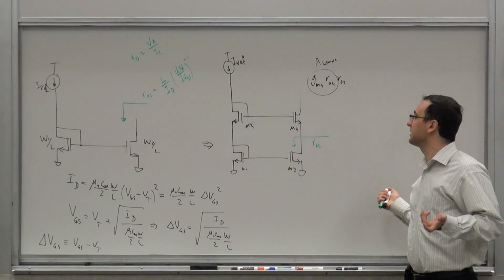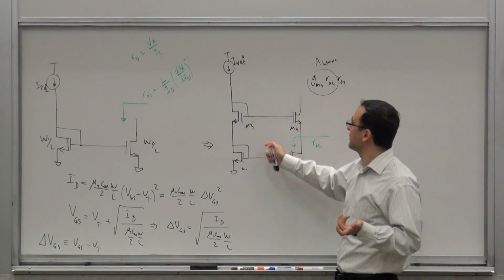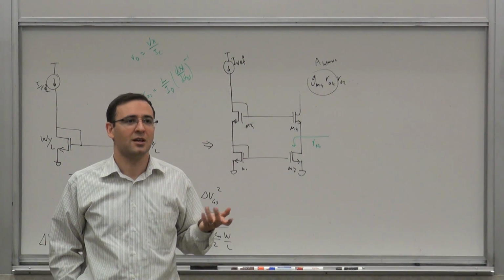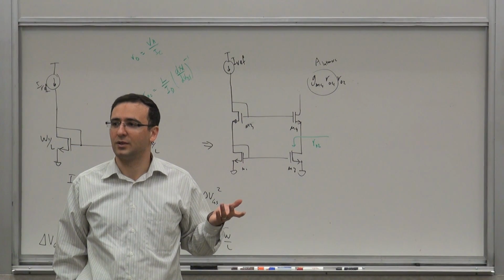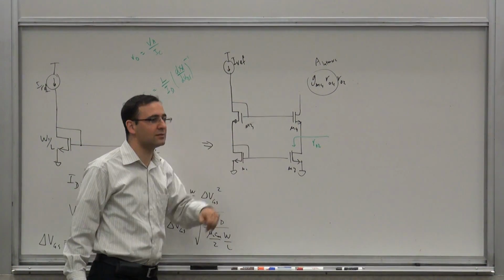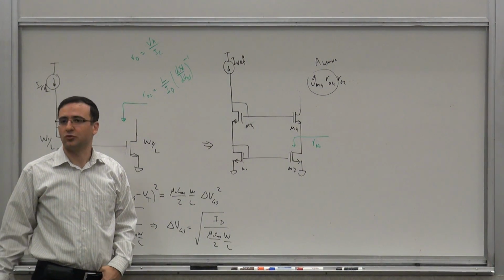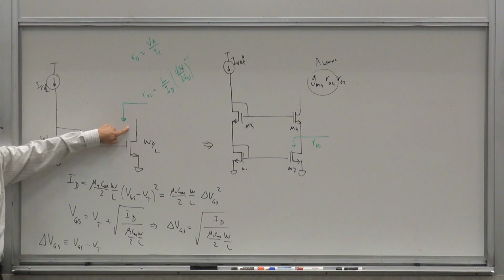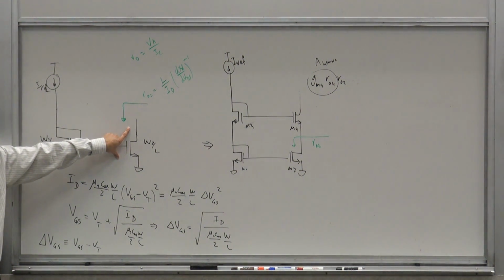So it seems like this is a really good thing. So why is it that you don't always do this? There must be a disadvantage. Most of the time, there's a trade-off involved, right? So what is the thing that you lose when you go from this to that? Headroom, basically, right? How low this voltage can go before it stops being a current source, or the output impedance starts dropping.